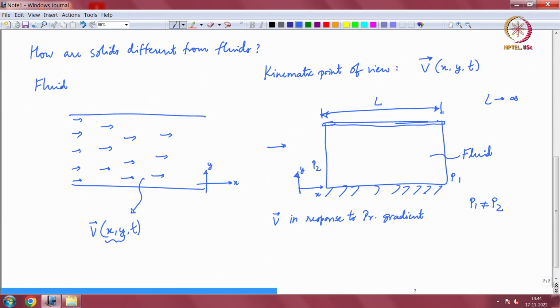That is one way of course, and the other way you have probably seen a Couette flow solution, plane Couette flow, is you take one of the walls, let us say the top wall in this case, and you apply a velocity to it, okay. I will just call this V0 bar to distinguish it from the bulk velocity, okay. So, if you do this, then you can also get a velocity in the fluid, so you can get the fluid to flow in response to a boundary velocity.